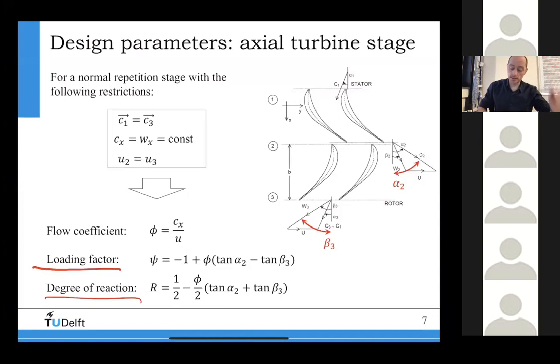And that's why I always said these angles for a turbine, for example, these are alpha 2 and alpha 3 in an ideal setting, right? If I have an ideal setting, I say that no matter what kind of mass flow I push through the stage here, right? The mass flow will probably be determined by the magnitude of this velocity. Is the mass flow this one here, or is it, let's say, the inlet velocity, or is the inlet velocity a much larger mass flow? Then I can say that the angle at the outlet of the stator, this one here, will be unaffected. It will not change, right?